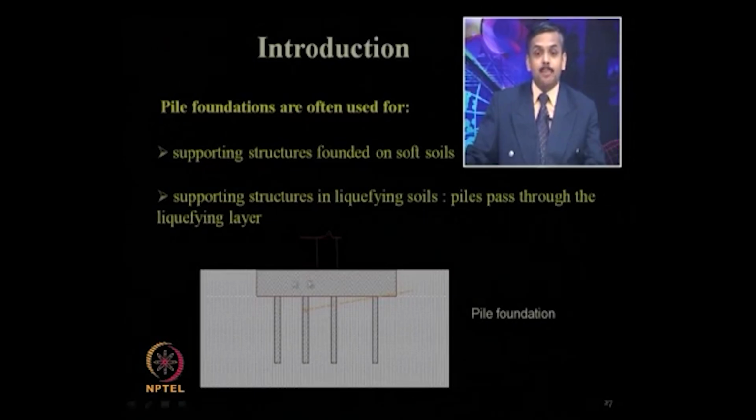But if that portion of the soil gets liquefied during earthquake condition, obviously it is not going to provide any kind of frictional forces or any kind of resistance. In that case, you have actually calculated in the design an overestimated value, which is not exactly acting at the site. That causes several times the failures of the pile.